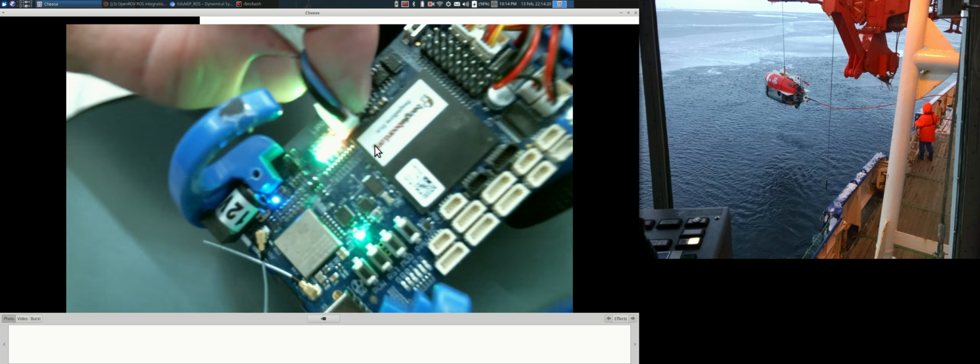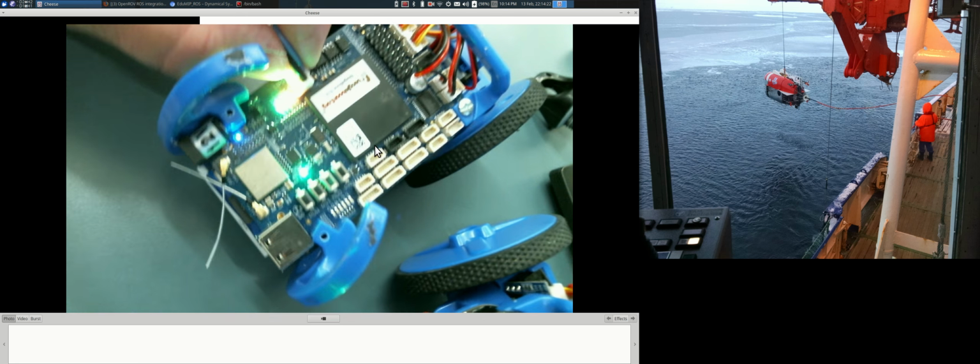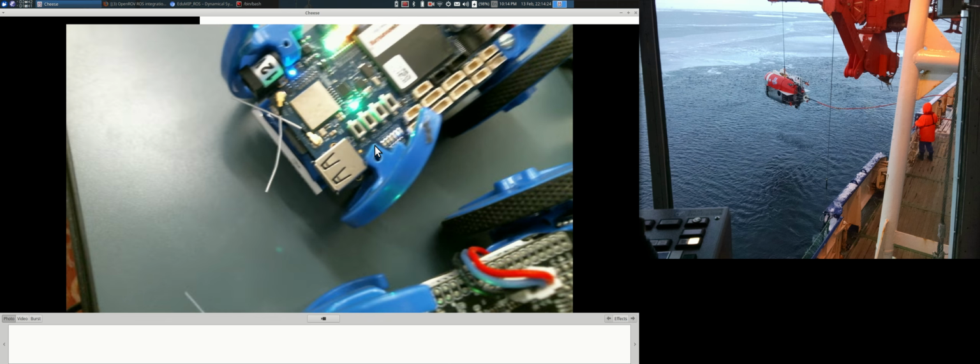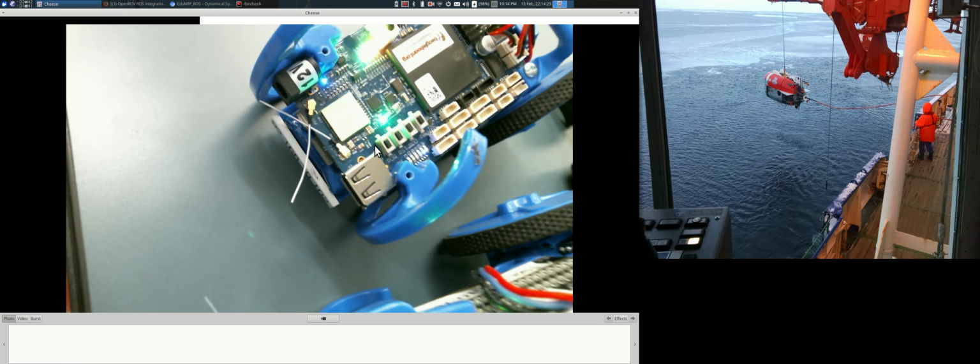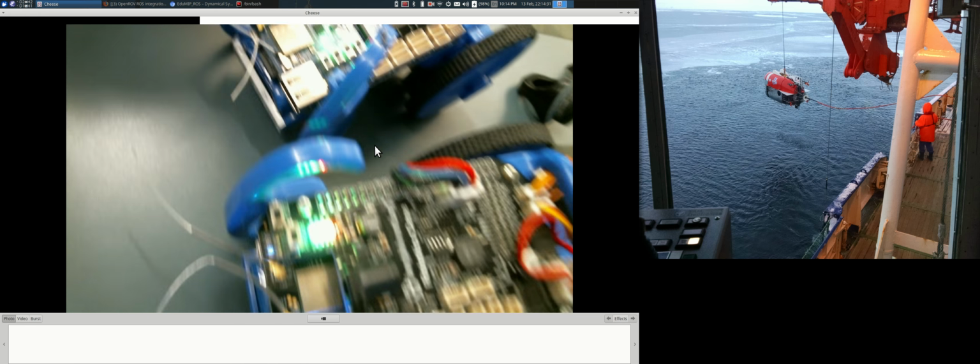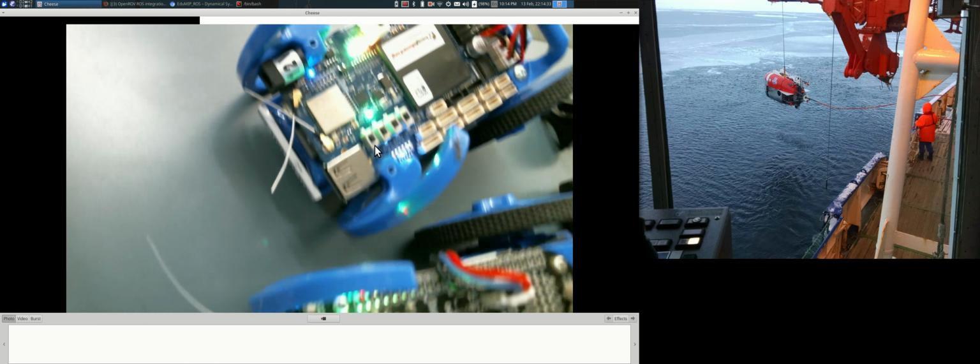And then unplug this battery connection here. That way, if you unplug the battery connection, when it's rattling around in your backpack and in the plastic case, if some piece of metal shorts out connections on the board, then it won't smoke the board. And then when you want to boot the thing back up, just plug in the battery connection and it'll boot right up.